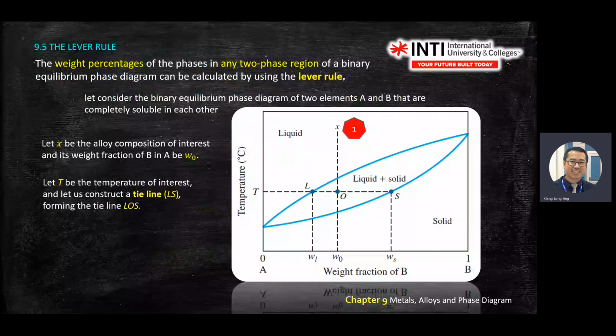We have the liquid and solid line, temperature and weight percentage. First step, you enter the graph with a horizontal line, which is the temperature of your interest.